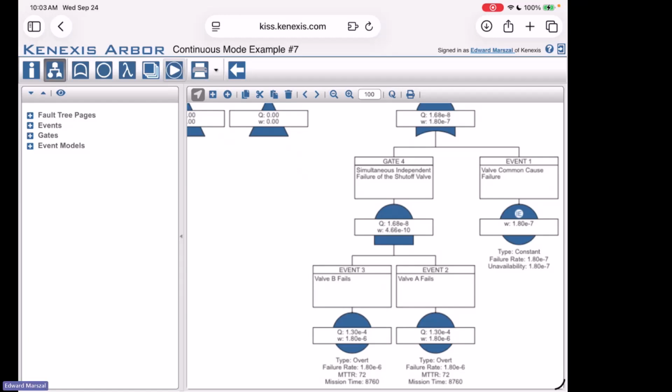Kind of going back to the beginning of the lecture, continuous mode is basically someone didn't design your chemical plant right, and you're using a safety function as a controller. And as a result, when that loop fails or very shortly thereafter, the consequence will occur. And we expect the consequence to occur before the next proof test. As a result, proof testing is meaningless.